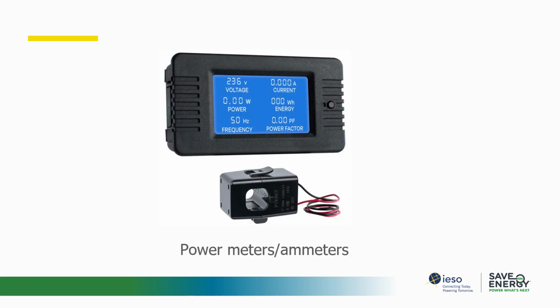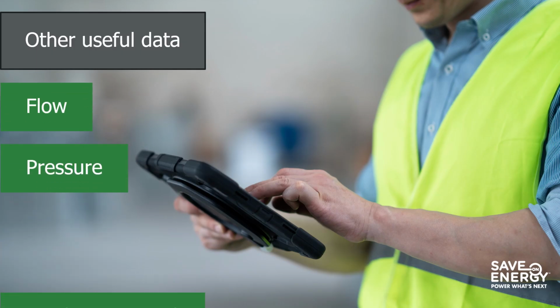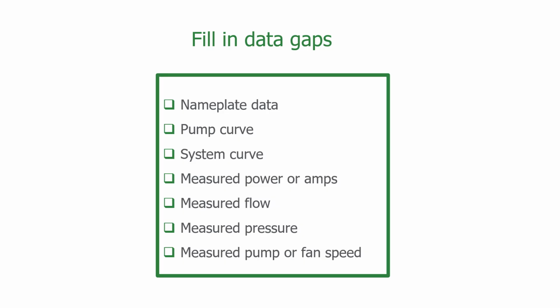Power meters or ammeters that measure and log electrical demand or current at short intervals, 5 to 15 seconds, are useful in establishing a baseline, particularly in systems where the flow is variable. Other data that can be useful to characterize operation and assess the impact of changes to the system include flow, pressure, and fan or pump speed. With this information, you can determine if you need to fill in any data gaps.